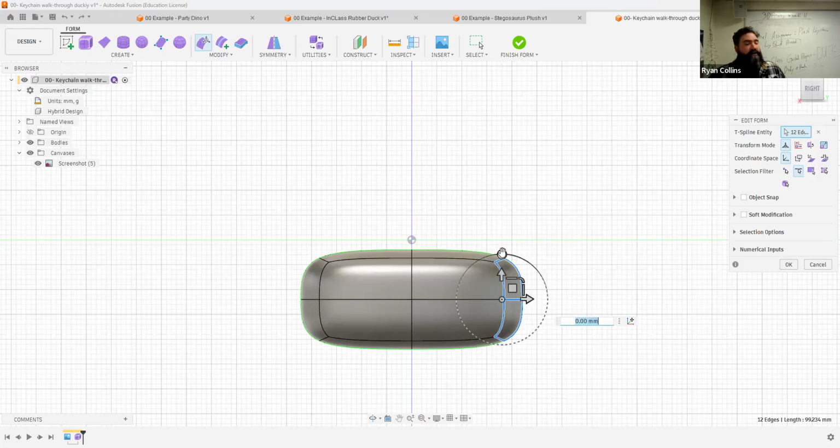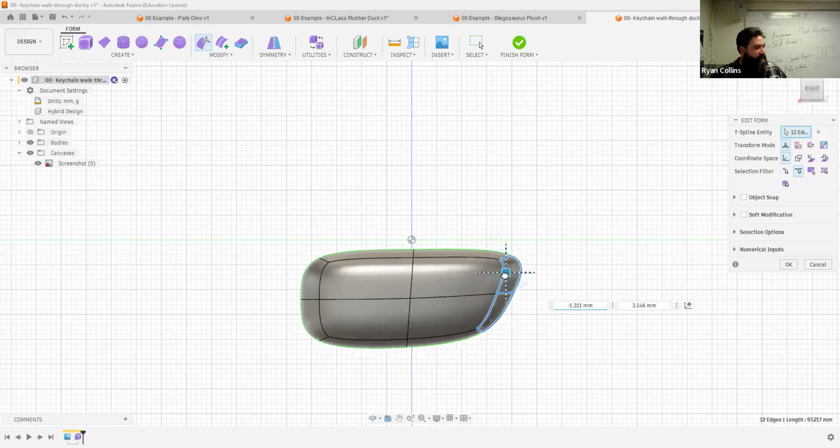Great. I'm going to use the rotate and just turn it a little bit. So I'm going to start to get that little tail section, a little sweep up. It started tilting down a little bit more. So I'm going to select by the square. That's the pan tool, free transform. And I can just squish it around however I want. We're trying to get that sweep up look. I didn't change it much, so now I just have a little bit of an angle. I am not worrying about what it looks like from the front or the top right now. Keep it isolated to one single view.